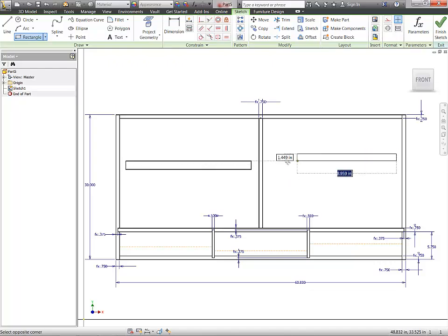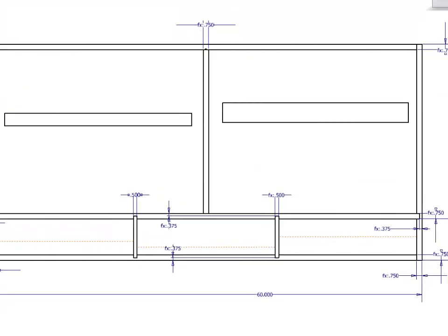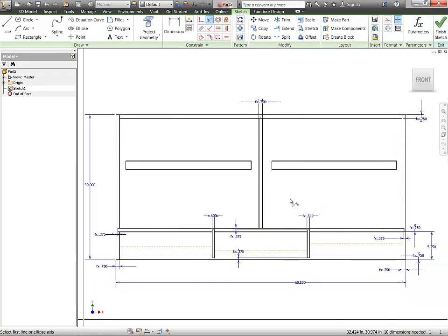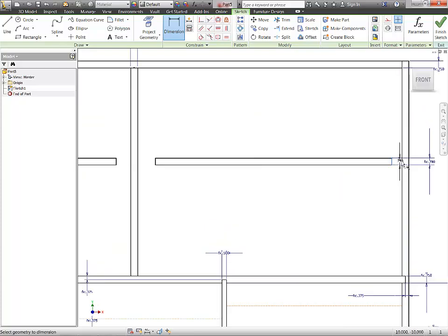Next, let's put a shelf in here. And what I've done before, again, we'll say the tops and the bottoms of these shelves are collinear, so they line up immediately. I'll also say it's 3/4 of an inch, equaling thickness. And now offset the edge, let's say it's a 1/16 of an inch, and we could type in a 1/16, we could type in decimals, we can type in metric. Inventor allows me to do any of those things.